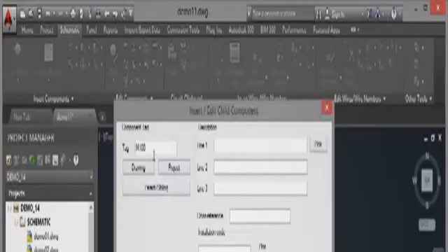So I click there, build up or down. I want to build that up because that's the lower wire. It updates, and as you can see, I've got a component tag there, so I'll just put M100 for now. Click on OK, and there's all the information. Maybe what I should have done there is perhaps update that component to tie in with the motor number. So what I can do here is I can click here, right click, edit component, and what I might want to do there is change that to 1003 and then click on OK.